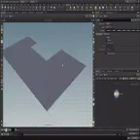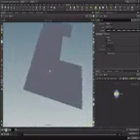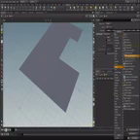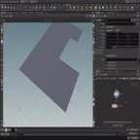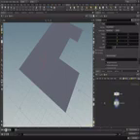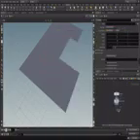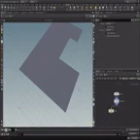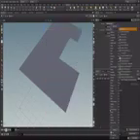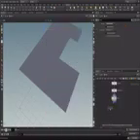Alright, and let's close this. Then enter perspective again by pressing 1. And now place down a transform node. In the transform node, the scale in the y direction we're going to set to 0. And then I want to place a sort node, just as some cleanup, and set it to sort by vertex order. Then place down a convert line.